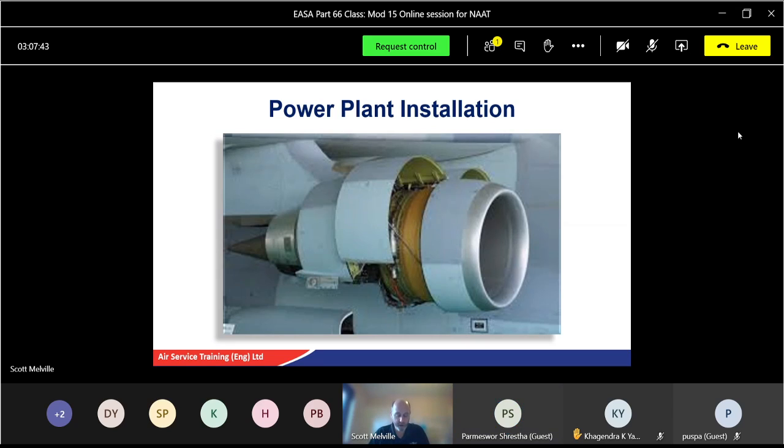Okay. How many power supplies does the FADEC have? Again, just random questions, just throwing it in the mix here for you. Two. Which are? They are the PMA and the 28 volt battery. Permanent magnet alternator and your standard 28 volts DC. When does the permanent magnet alternator kick in, or when does it activate? During startup. What percentage of RPM? 50%. Yeah, good. So not quite self-sustaining, but it's fast enough to switch over because the alternator is going faster on the gearbox.